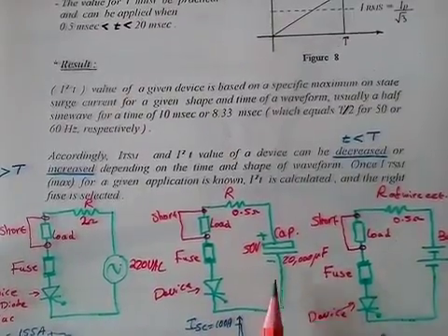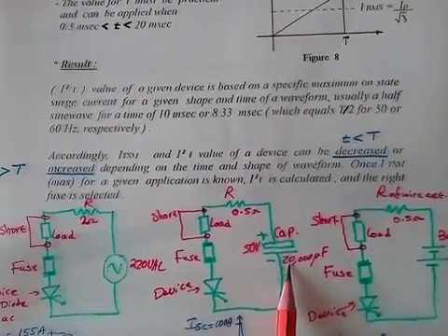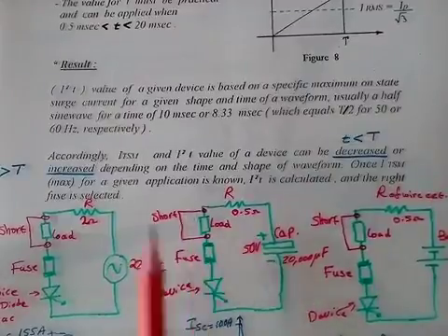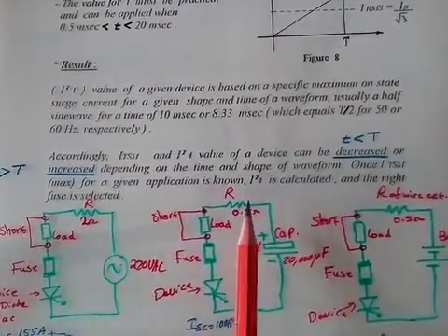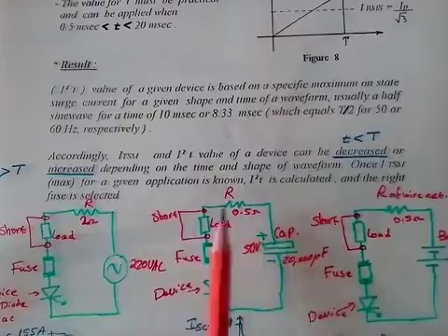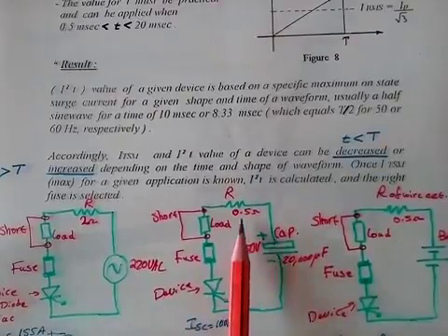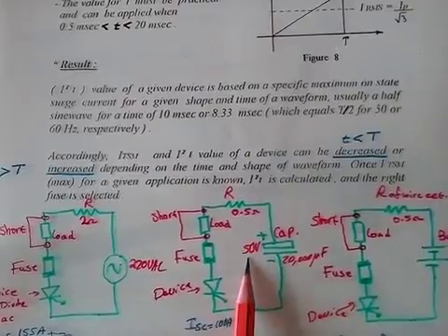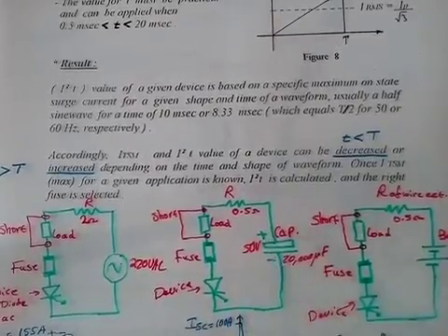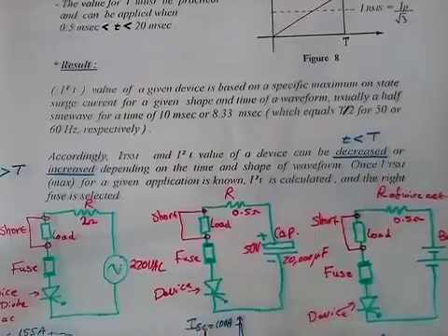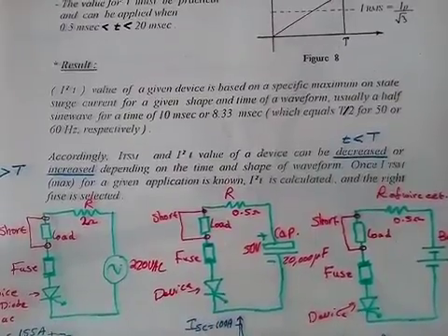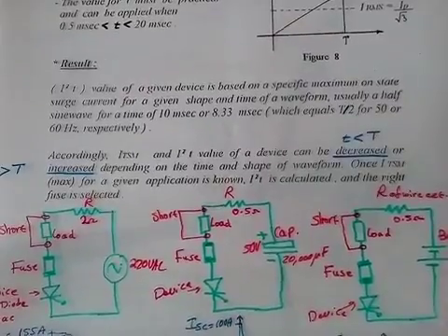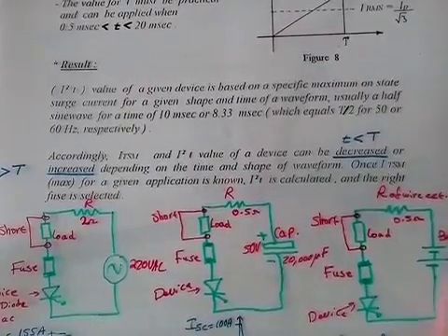In this case, for example, suppose you have a cap that's going to discharge through the load, which was shorted, like the one before. So you have that resistance of the wire, or the resistance of the circuit. We have it's about 0.5 ohm, and that cap was charged up to 50 volts. So you have that peak current through the device that needs to be protected, would be about 100 amps.